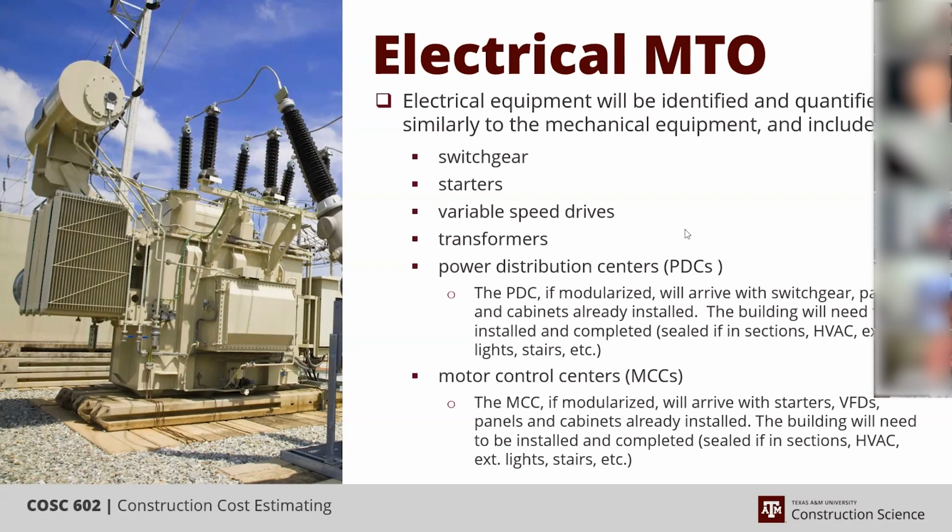Versus when it comes from underneath, you can put a bank of switchgear on either side of that opening in the floor, and then it'll come up through the floor and enter the back of the switchgear, the panels, the cabinets. And then the items that need to move to the panels can be wired to the outside walls. So you've got a walking path that kind of circles that center. It's not as easily done whenever the wire is coming in from the side.